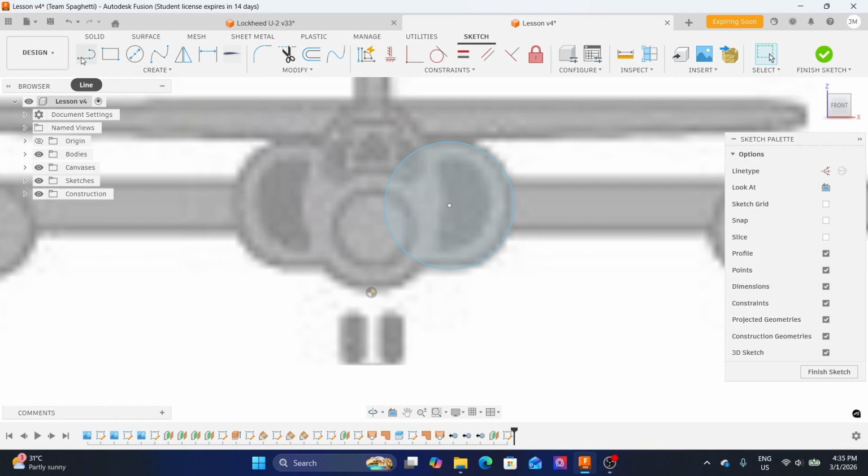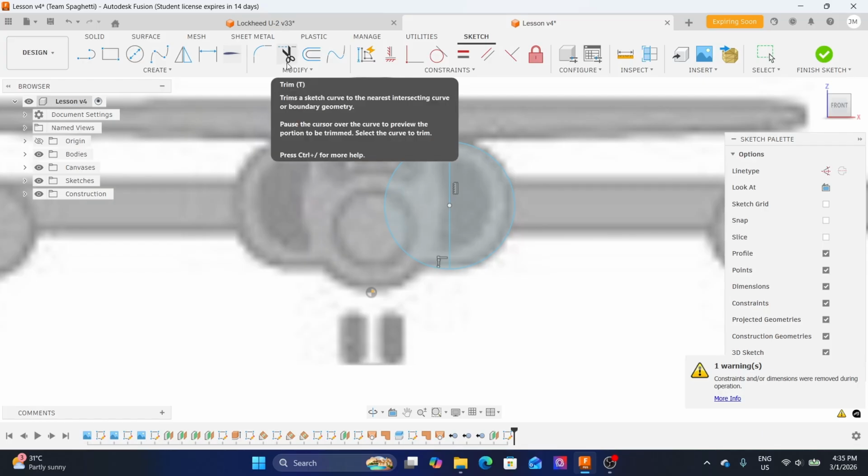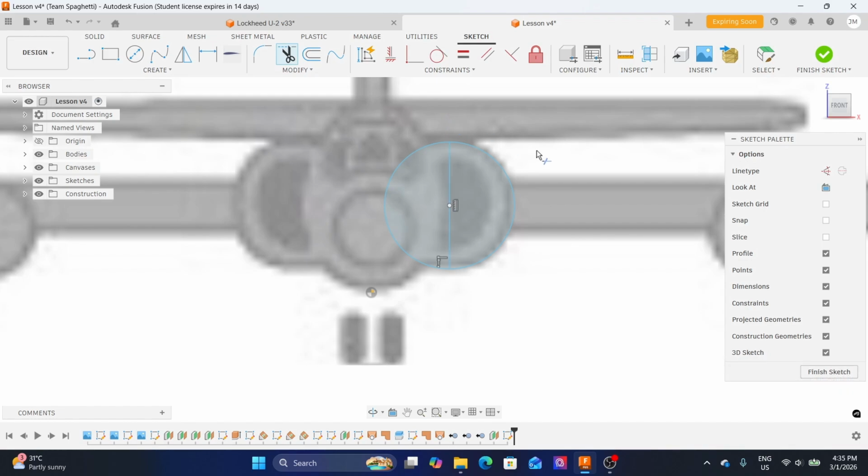Let us proceed on creating a line here from the center point of the circle that we have just created. The second point is right here. Press the check mark or escape on my keyboard once done using the tool. Then I'll go here to the modify tab and select the extend tool. I'll just extend the line here, and then I'll trim the excess line here. There we go. Press escape once done. Then we'll convert this line into a construction line. So the line type is going to be construction line.